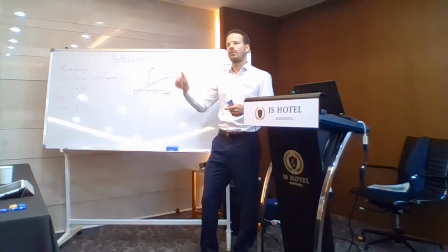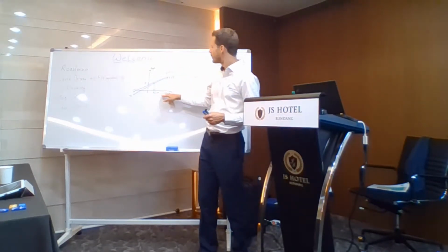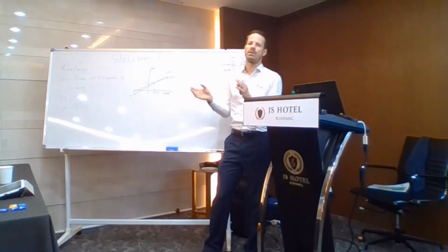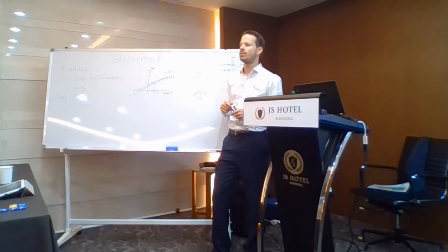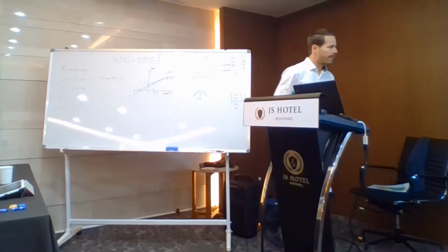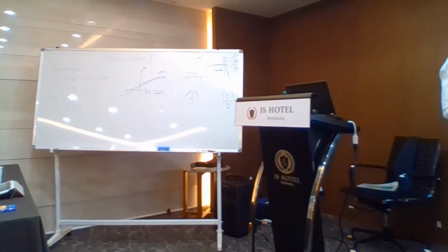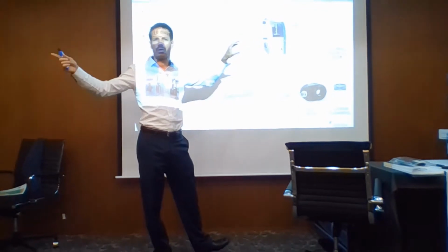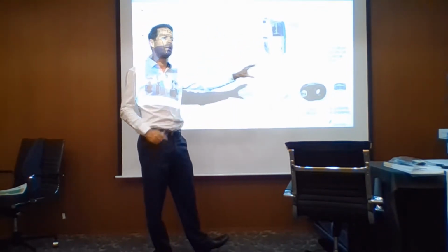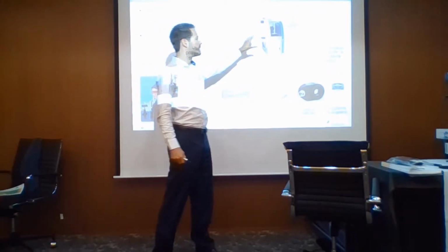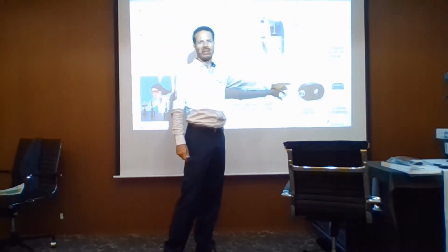But if you then check the current, it will go down from 200, maybe to 180. So there's the real-time compensation of the temperature change by the driver. The principle is we measure the wavefront quality and we measure the optical power versus current characteristic of each lens. During production, we save the calibration data onto the lens.